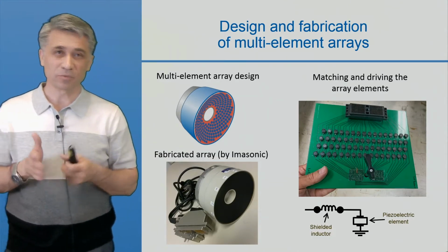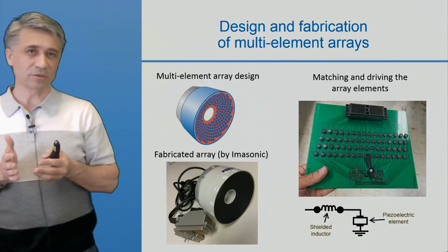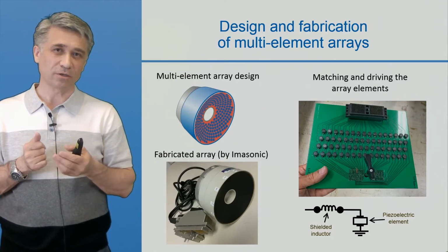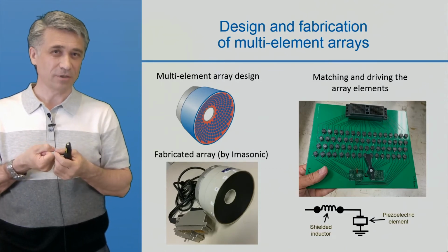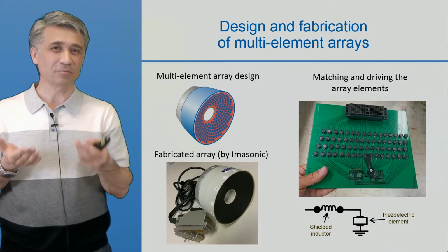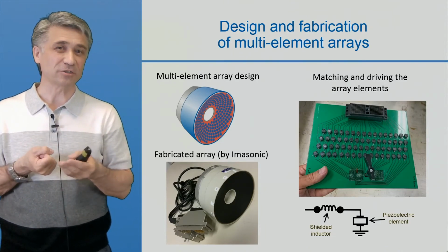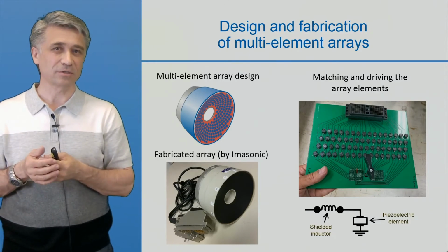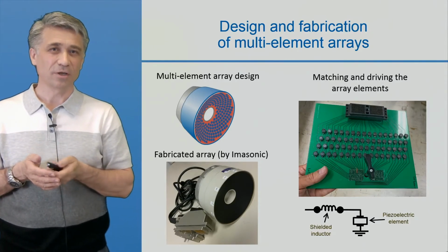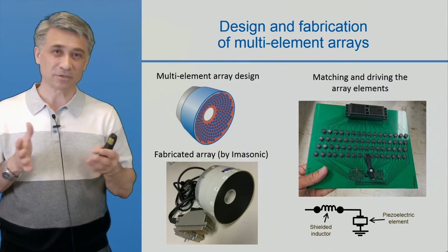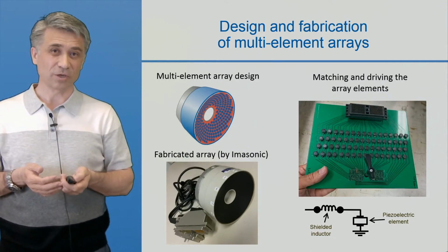Also, one technical thing that I should mention: when you drive the piezoelectric sources, you need to be sure that the electrical source of each element sends the energy to the element in an efficient way. People say that they should be electrically matched. For that, there is a special circuit. This is a matching network, and here is an example of how it looks. You see many elements, and this is just to make it more efficient.